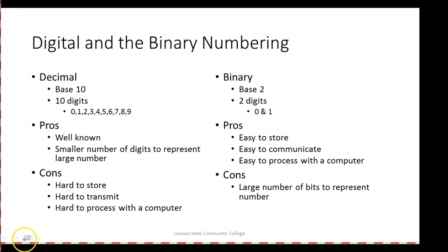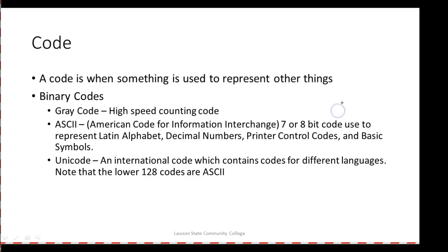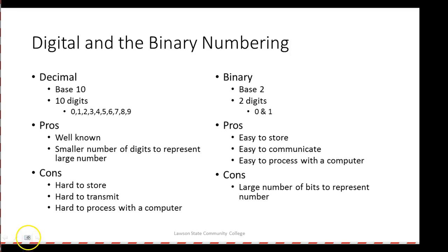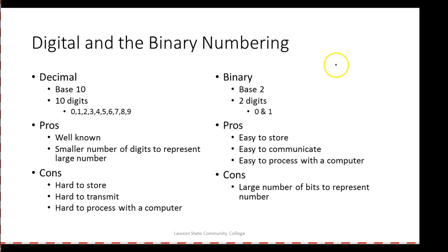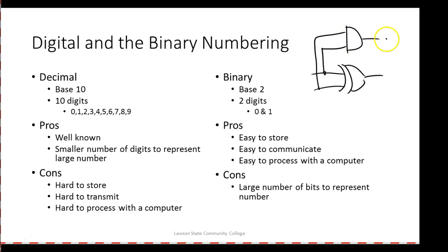So the circuit to add, I'm trying to find my drawing thing because it's right on top of this. So this is a binary adder. We come up here, go through an exclusive OR, and then we come over here. That would add them, and then I come up here and I take care of my carry, and that's an adder. That's an adder for binary, 2 binary bits. That's all there is to it.